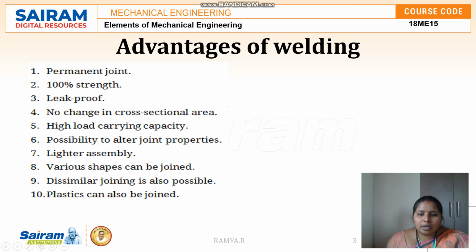Now the advantages of welding. It creates a permanent joint, 100% strength, leak proof, no change in cross sectional area, high load carrying capacity, possibility to alter joint properties, lighter assembly, various shapes can be joined, dissimilar joining is also possible, and plastics can also be joined.